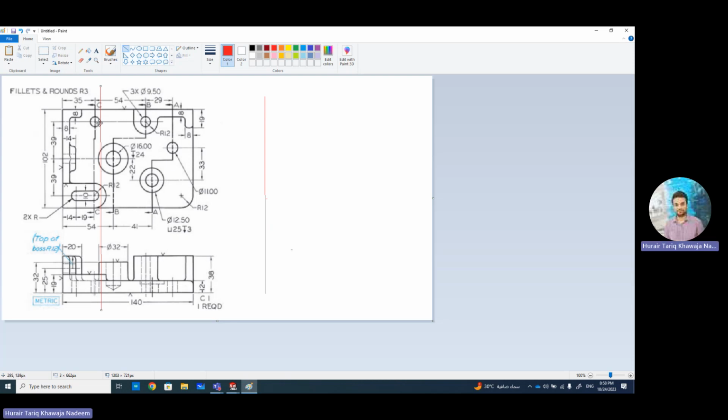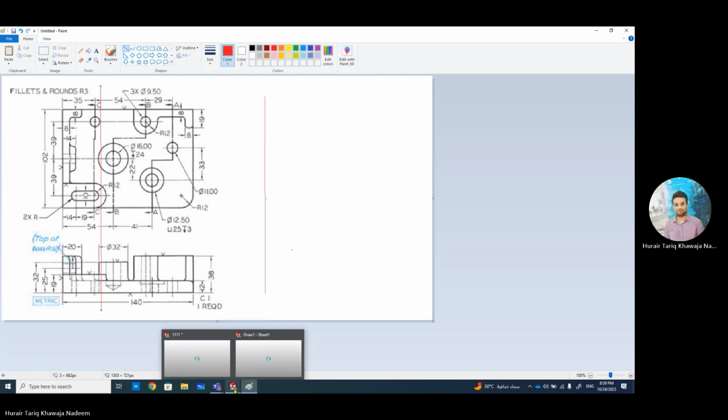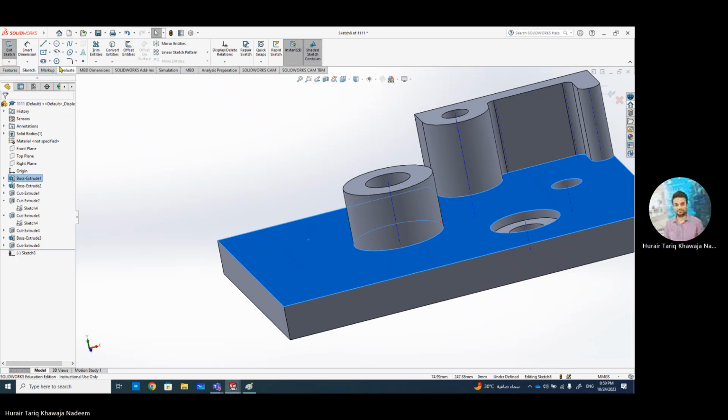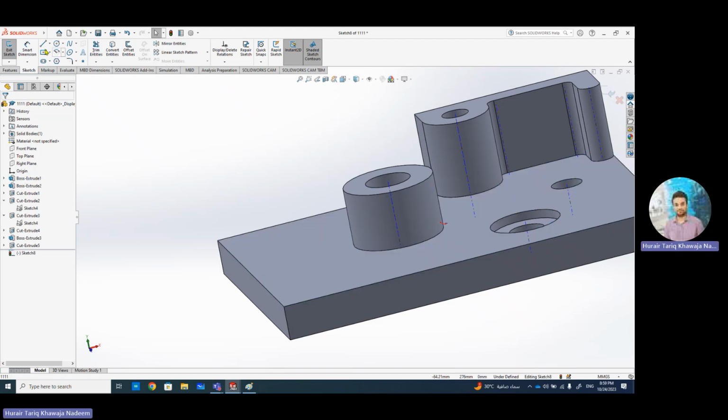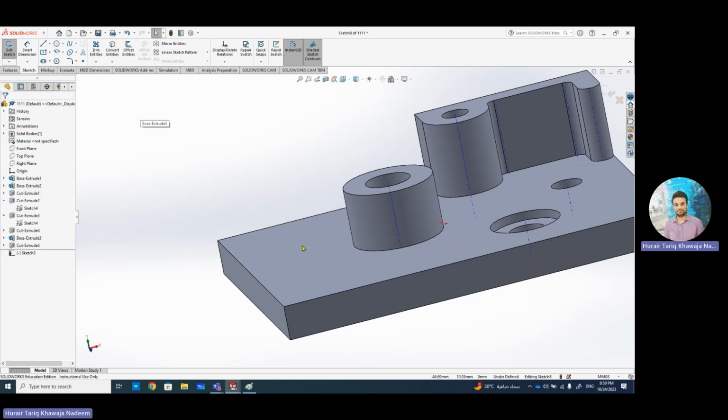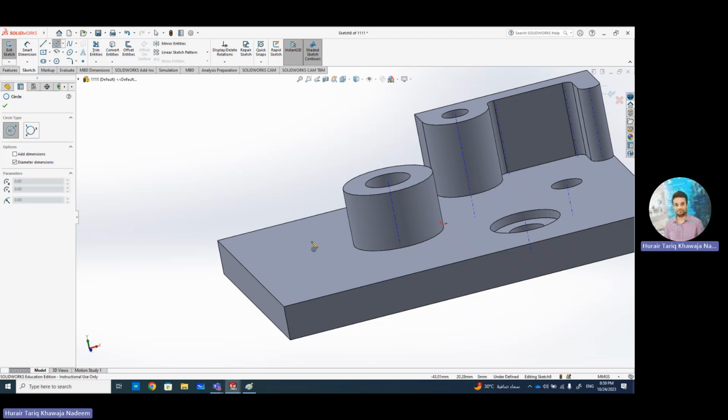So let's make the hole which is over here, and we know that it's actually a cut. Okay, so there is a hidden line. Now, this solid line is actually because of this feature. Okay, let's make that hole first of all. It's a small hole. Sketch on the surface. Make a hole. This is sketch 8. I'm clicking on this and making a hole.